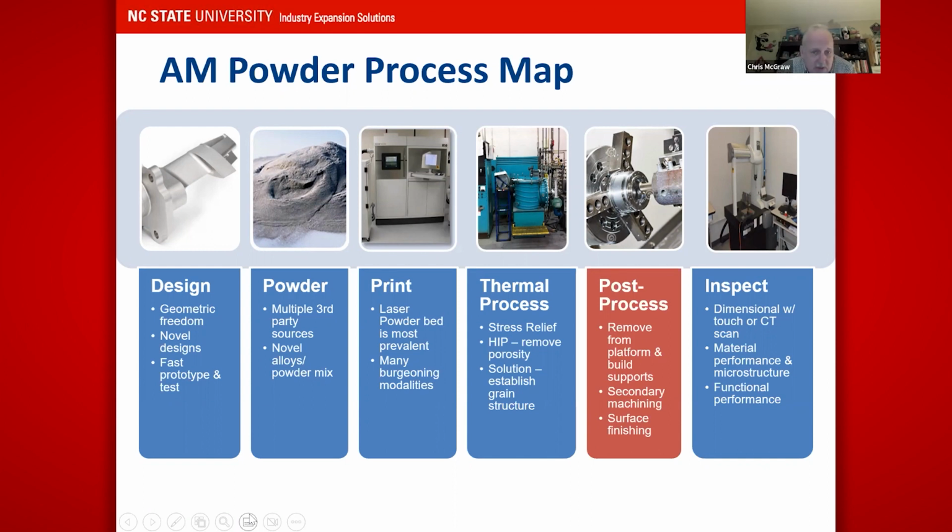Once it gets through the machine, it may have to be heat treated, among other things. It may be connected to the base that it was made upon. You may not have the finish that you want. You may have to do some polishing. So there's going to be post-processing. I don't want to give the illusion that 3D print, additive manufacturing, is the catch-all for everything. It's going to help, but it'll get you to a certain level, and then you may have some finishing operations toward the end.